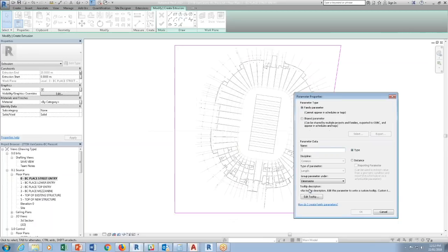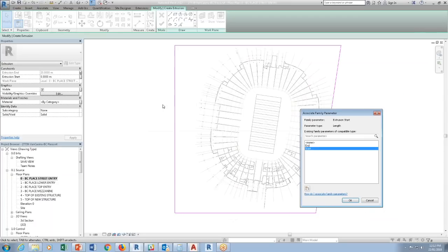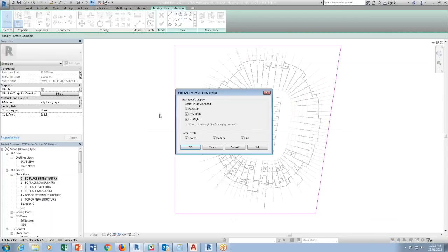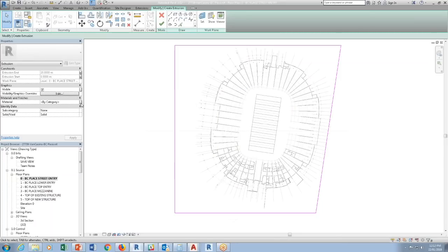What this does is that this means how much you want your property line to project. So I'm just going to put a couple of parameters. Now, one thing I would do is make sure that it will not show up in plan. The minute that you say you want it to show up in plan, it's going to hide your model. So if you want to do it, just turn it off.